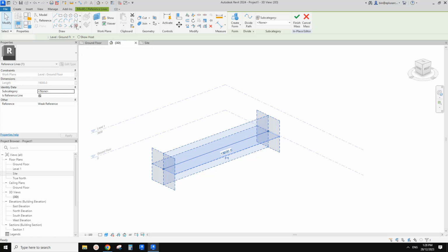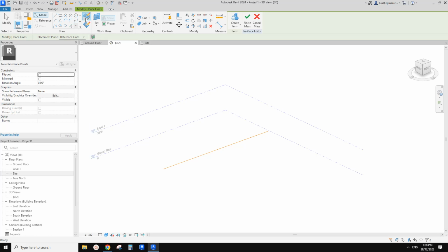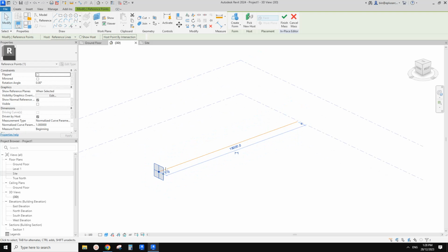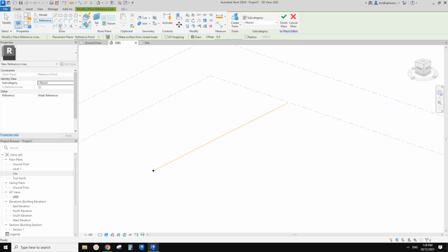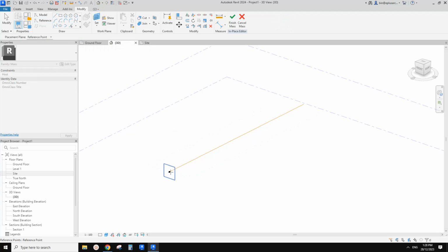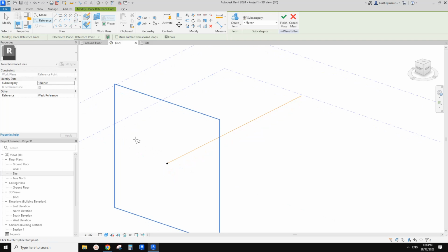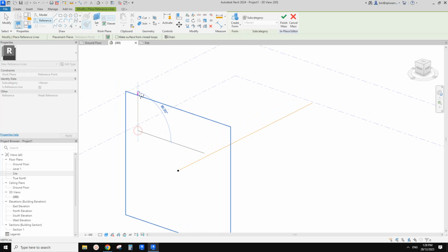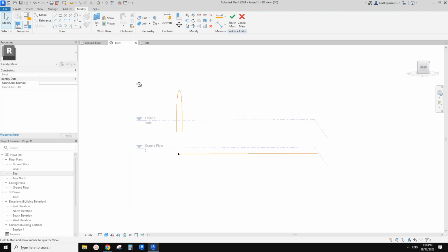Now for profiles we need to create a point, use draw on face, and then place onto this reference line. We can just drag this one along this reference line, and then place a profile. For the profile, I'm going to use spline. Not spline through points, use spline. You draw on work plan, set work plan, pick this vertical work plan. Now I'm going to roughly, I know this side is a little bit higher, so roughly just draw a shape. Okay, something like this, right?